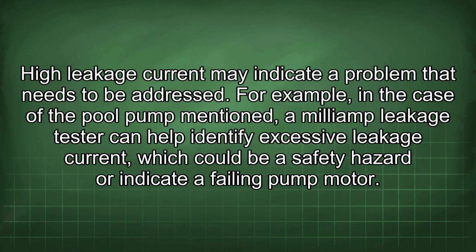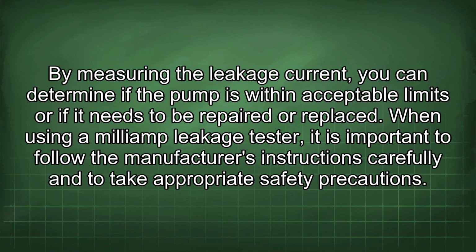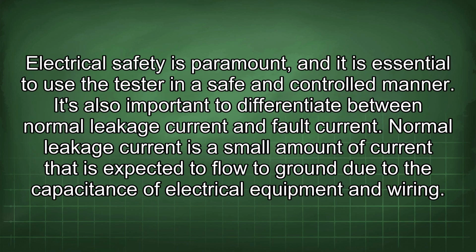For example, in the case of the pool pump mentioned, a milliamp leakage tester can help identify excessive leakage current, which could be a safety hazard or indicate a failing pump motor. By measuring the leakage current, you can determine if the pump is within acceptable limits or if it needs to be repaired or replaced. When using a milliamp leakage tester, it is important to follow the manufacturer's instructions carefully and to take appropriate safety precautions. Electrical safety is paramount, and it is essential to use the tester in a safe and controlled manner.